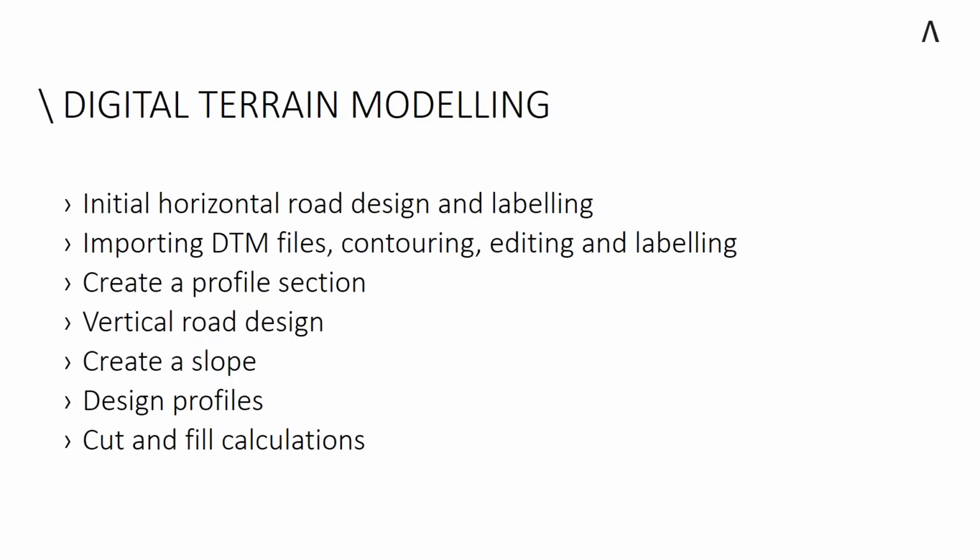Okay. In Allplan, we have various ways to create those digital terrain files, not just constrained to one particular format. In many countries, there are free-to-use versions of maps. Here in the UK, we have an open source point listing that gives our Ordnance Survey maps height at 50-metre intervals. And in theory, if we were to put all of those tiles together, we could create a full-on digital terrain model of the United Kingdom.